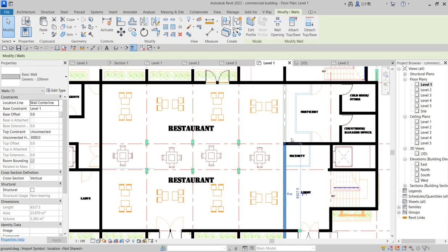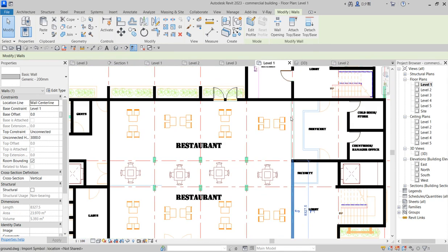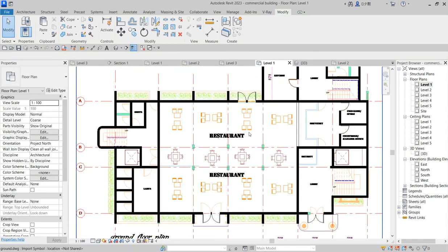So we are done with this, so we push to some level. Now there are some walls that need not reach the top, like this surface strip wall. So we create them by putting it here. You change the height from here before you start the drawing. I'm changing it to just like 900, just a little bit above ground. So you see, this is what we'll be having.